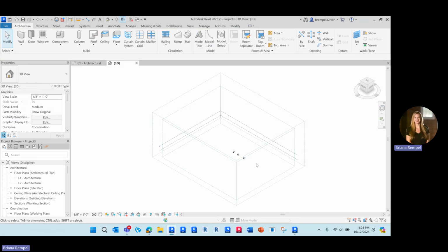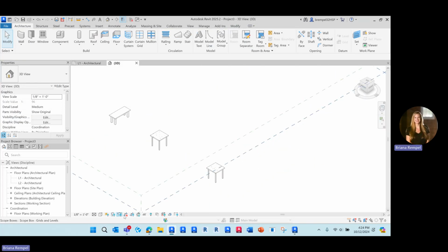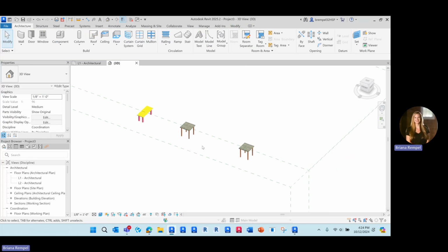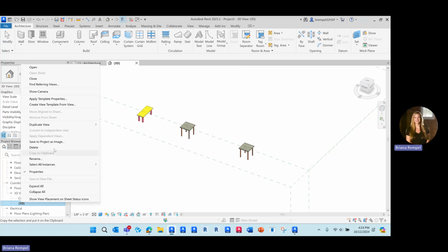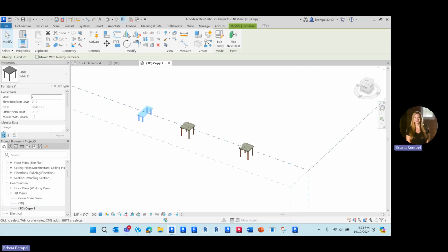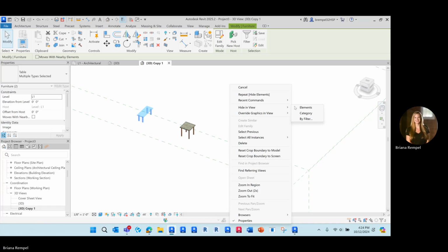All right, now take a look at it in 3D. Now I have 3 different types of that table. You can make another one for that. If I wanted to put these on a sheet and have a view tag for each one, I would duplicate this 3D view 3 times, or twice, I guess, so you would have one of each. And then I would hide in one of them the other 2 tables. And then in this one, I would hide this table and this table, etc.